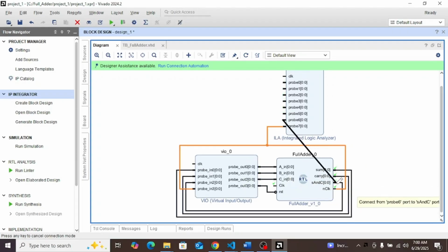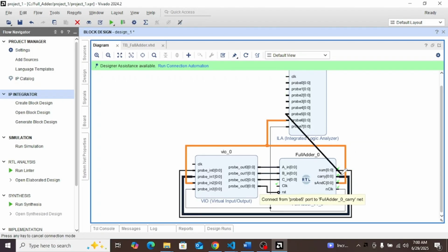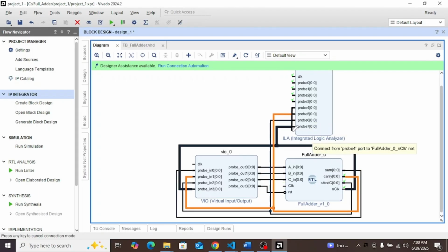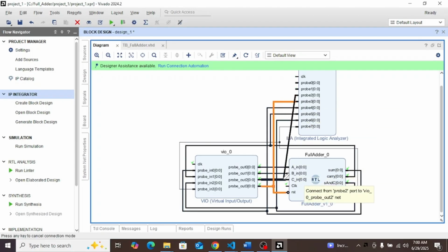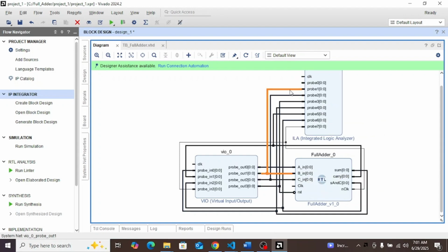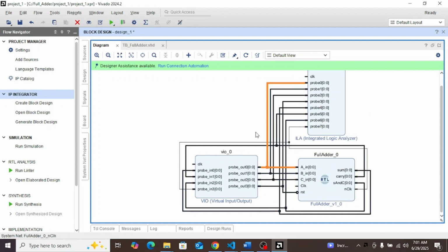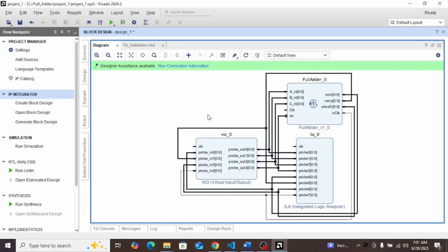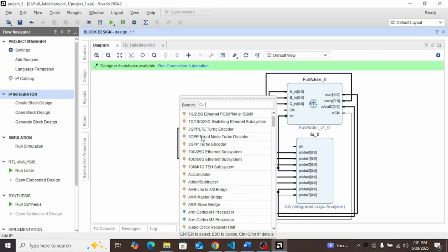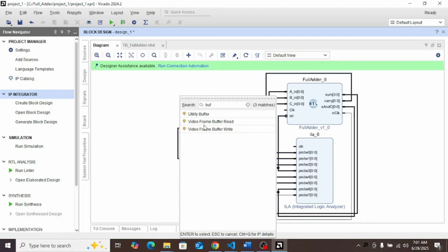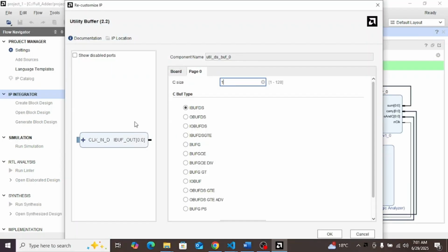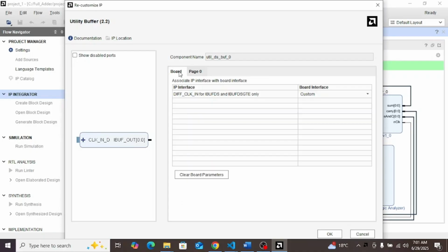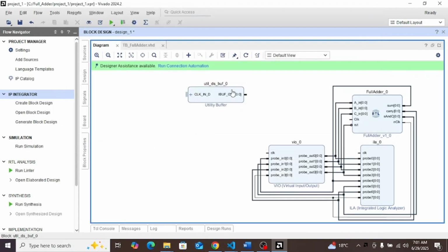But for the clock, we're going to have to get another IP here, because the clock of the ZCU104 uses a differential clock for precision and noise immunity. So this IBUFDS essentially will be able to help us to connect to that differential clock of the ZCU104.